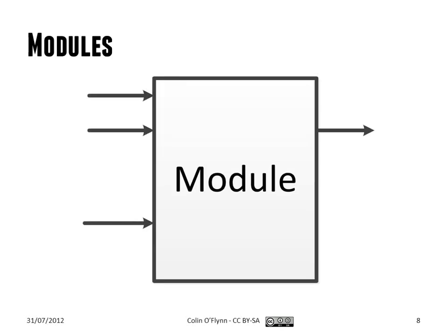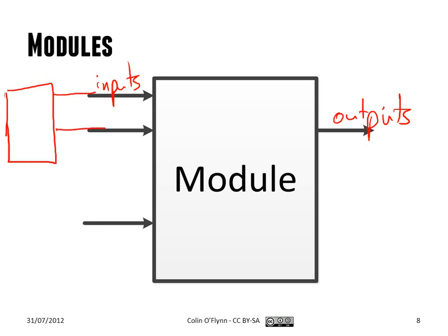They almost always use this idea of modularity and modules. A module, and there are different names given to it, is basically just a block. In that block, we'll have inputs and outputs. So it's very much like the sub-circuits you've been using in the labs for the schematic. You create a sub-circuit that has a specific function, it does that function, and you can connect it up. When you connect a big design, you might have a whole bunch of these different modules all wired together, and you'll have adder modules, memory modules, all sorts of stuff. In that way, you don't have one massive design, but you create a block, you test it, it works, and then you put it into a bigger design.